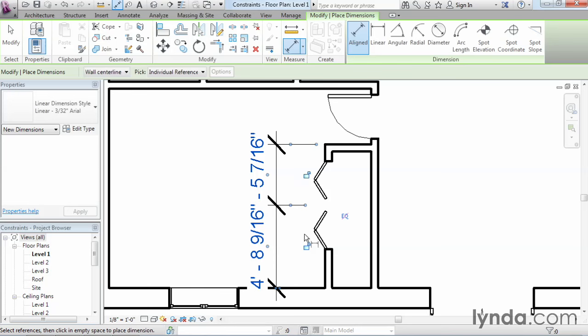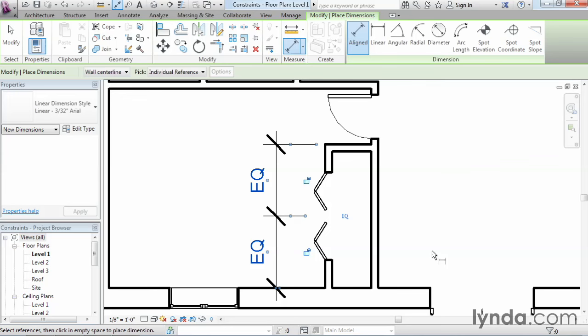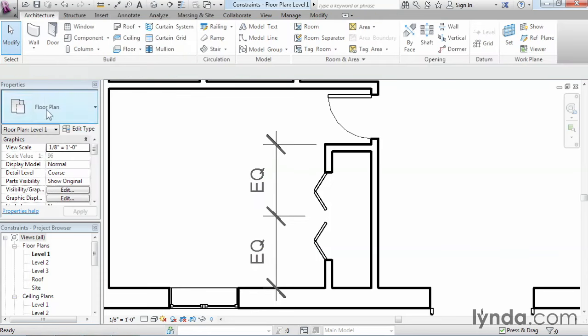There's a few little controls floating next to the dimensions. I'm going to talk about the locks in just a few moments. We're going to look at this one right now, Toggle Dimension Equality. If I just simply click that, that will actually move the position of the door and center it between the 2 witness lines that I asked for. I'm going to click my Modify tool to cancel out of here.